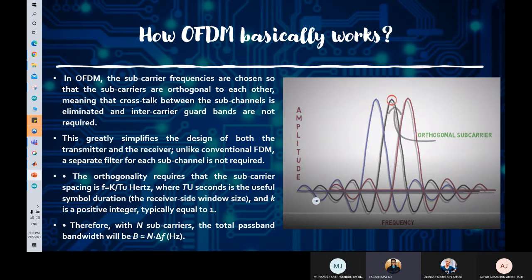Also, two or more multiple subcarriers act independently. They work independently and don't depend on any other sub-channels. So in that case, any neighbor signal would operate with no interference between them. OFDM makes use of the bandwidth properly. Thus, it offers high data rate transmission, and that is why most telecommunication industries use OFDM as their basic method.